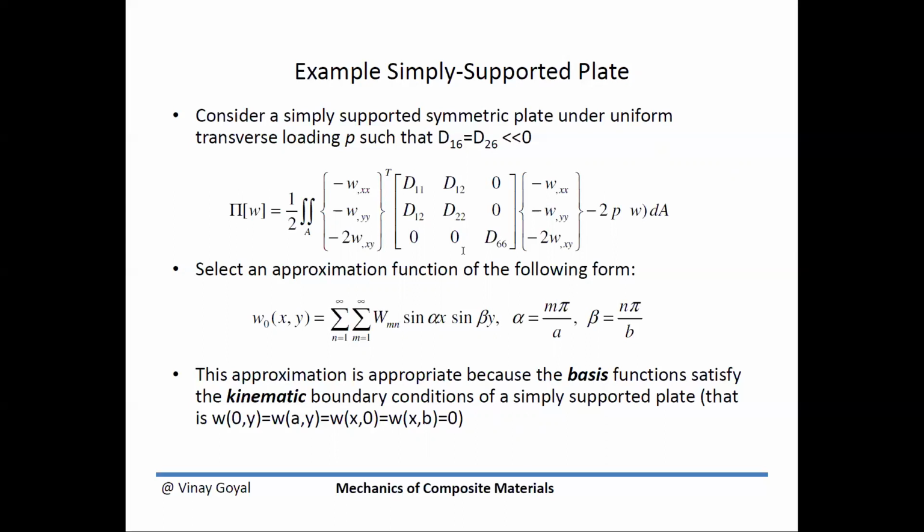And if I don't apply any in-plane loads, I don't expect the mid-surface to expand or stretch or compress. As a consequence, this is the total potential energy. So just borrowing from the previous slides that we discussed, I'm going to select an approximation function of this form. And this WMN is not known.